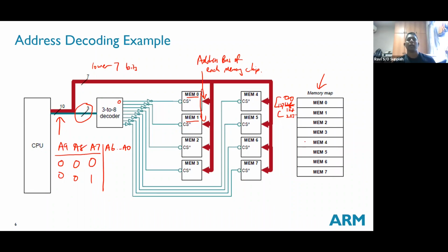They will look at what memory systems and what peripherals they need to put in, which address locations they need to map them to, and then based on that, they design a decoding circuitry so that when this address is put on the address bus, this particular hardware gets activated. All this is the back-end work you need to do if you want to design your own system from the processor level up.